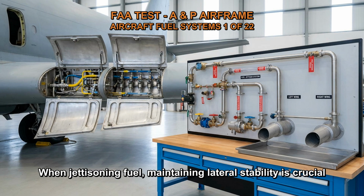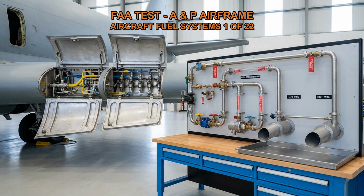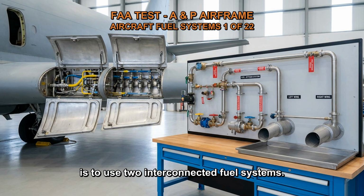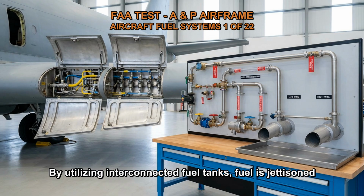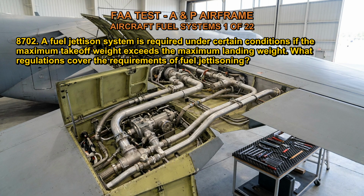When jettisoning fuel, maintaining lateral stability is crucial to ensure the aircraft remains balanced and controllable. The most common method employed for this purpose is to use two interconnected fuel systems. By utilizing interconnected fuel tanks, fuel is jettisoned equally from both sides of the aircraft, maintaining lateral balance.